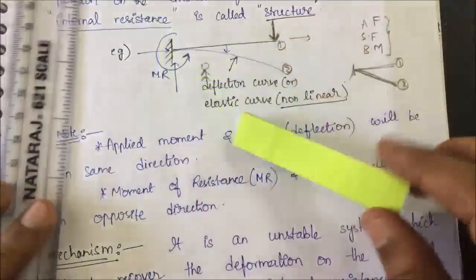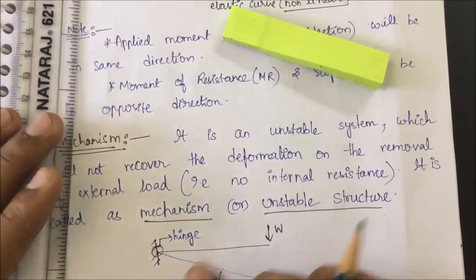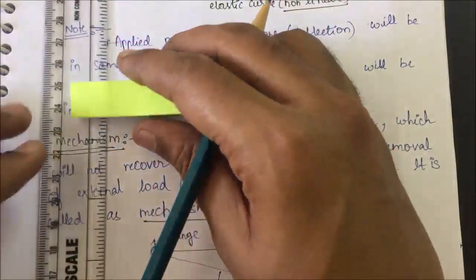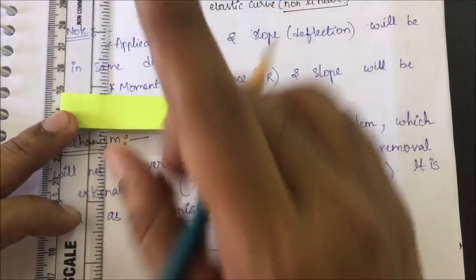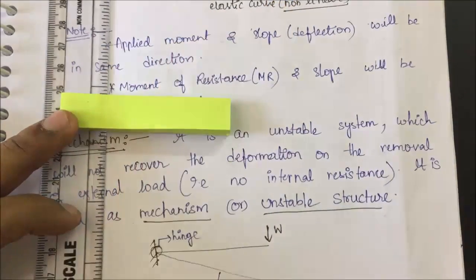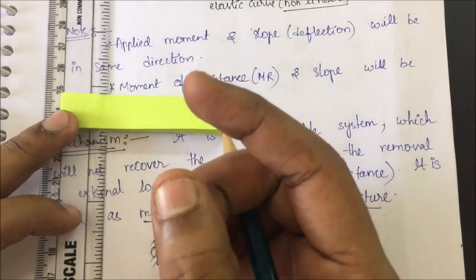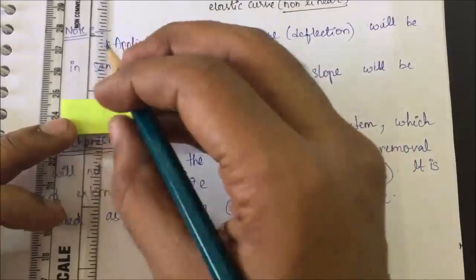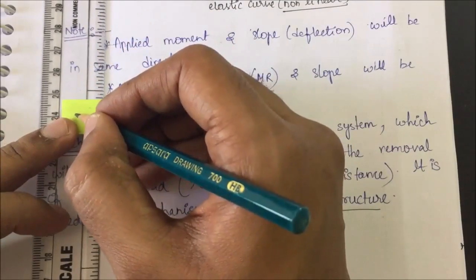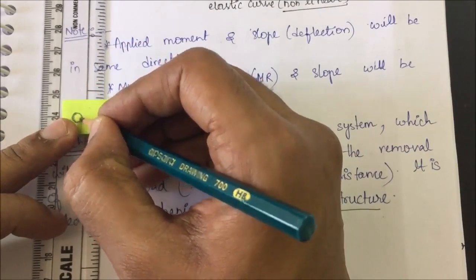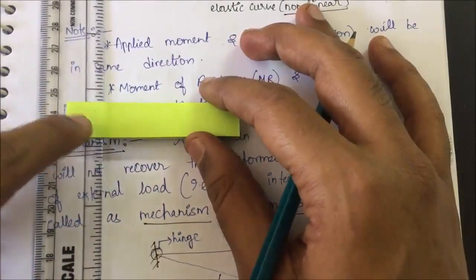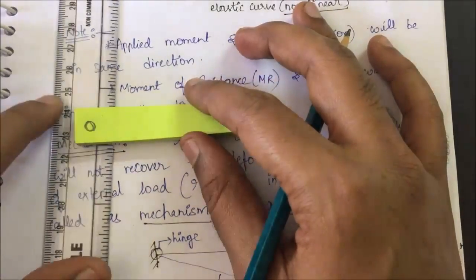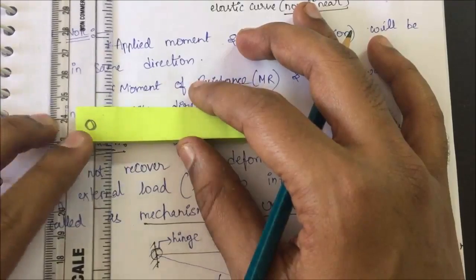But in the case of a hinge, you attach your beam with the help of only one rivet or only one bolt. Your drafter, the engineering drafter, is easily movable like this, right? Because it is also a hinge support. If you see clearly, there is a bolt passing through the beam and through your support. This type of thing we call a hinge support.